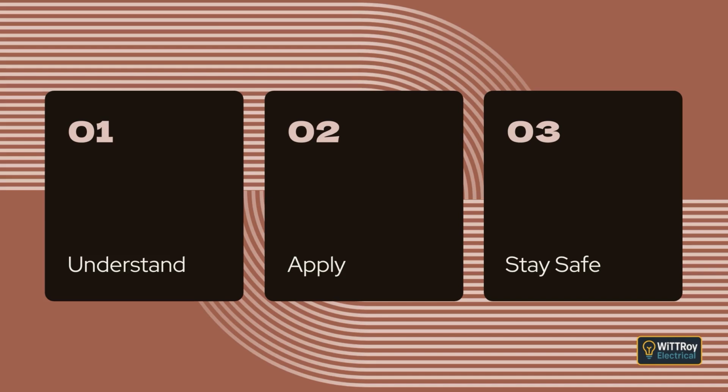Clause 2.9.2.5, Restricted locations. There are some places where you are not allowed to install switchboards because it is unsafe or impractical. A switchboard must not be installed higher than 1.2 meters above the ground, the floor, or a platform. This is to make sure it can be reached safely. There is an exception if access to the live parts has been arranged safely under Clause 2.9.3.1. A switchboard must not be installed near water containers or near fixed or stationary cooking appliances. Water, steam, or heat would affect the switchboard.